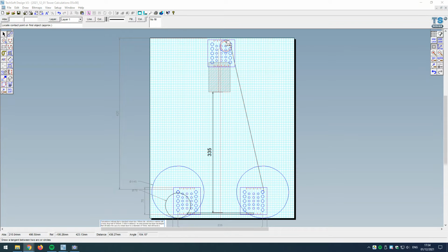and I've also made sure as well that as the drive string in effect unravels off this back axle, runs up over the pulley and drops down, the top pulley here is offset slightly so that the string attached to the mass will allow the mass to then fall directly down into the middle of the vehicle. I've compensated here for the size of the mass. I believe these calculations are all correct based on our 1 kilogram hangers.